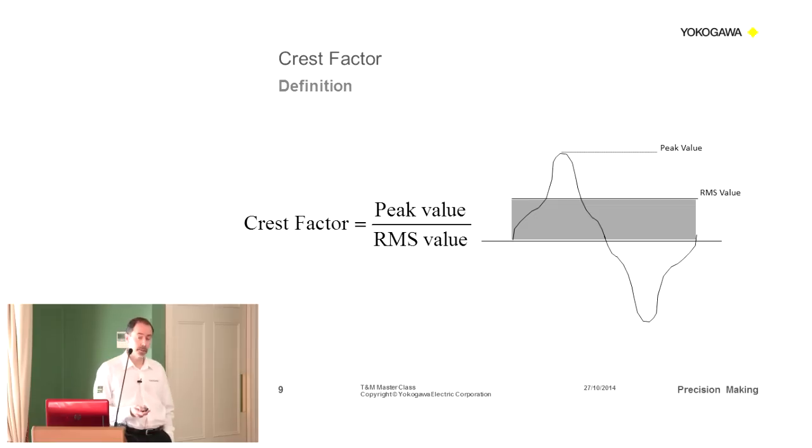So you can see that modern devices, instruments that go into standby power, for instance, where we're talking about 1 watt or even half a watt, have very high Crest factors and quite low power factors as well. So it actually presents a big problem to the instrument you're measuring power for, because your ranging may be dictated by your RMS value, but your dynamic range must cover the peak value.